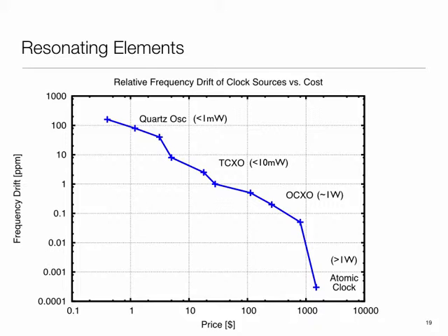So if you have a system which is going to go to sleep for a long duration of time, and you are worried about power consumption, then you should be using a very slow frequency. Your PCs or laptops have this thing called a real-time clock, which is a separate chip, consumes microwatts of power, but its frequency is extremely low. What do you think is the penalty of having a very low frequency oscillator while the system is asleep?